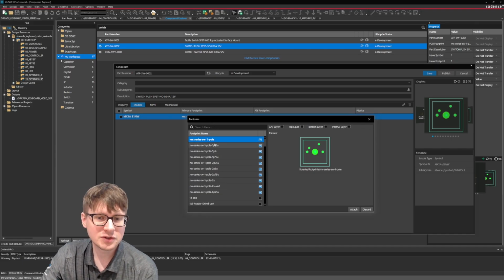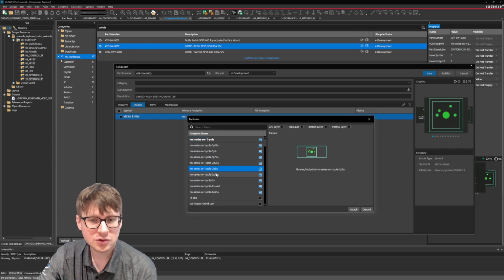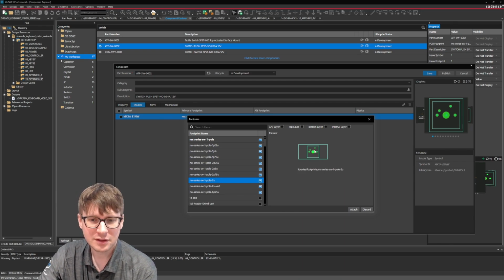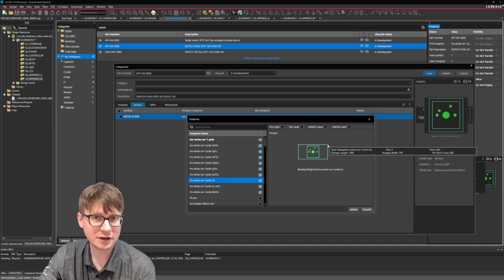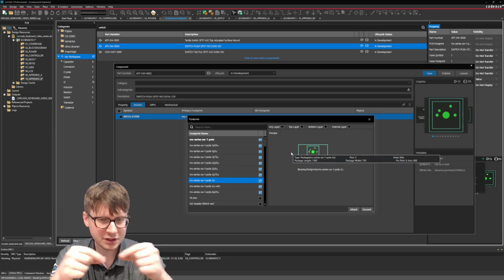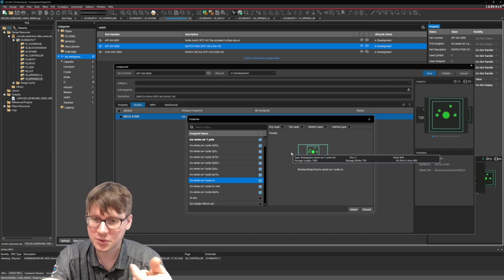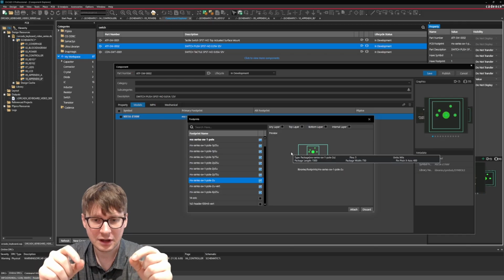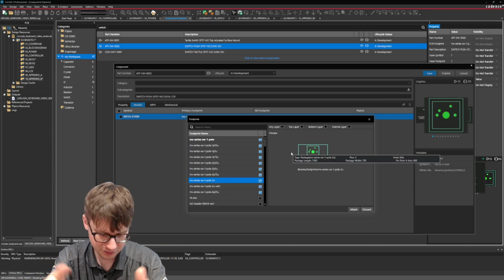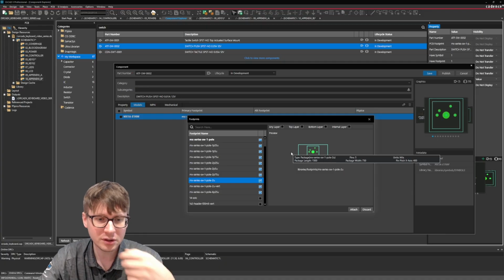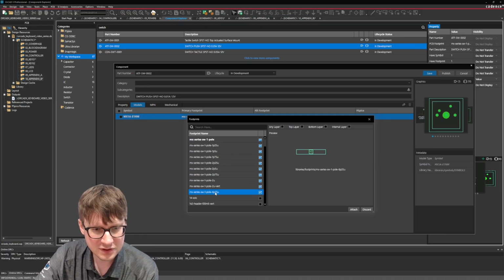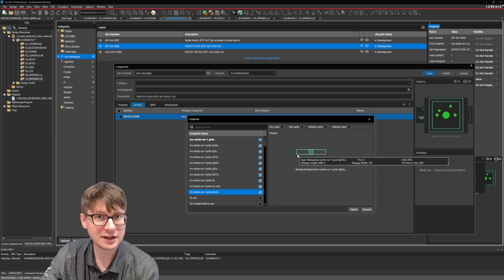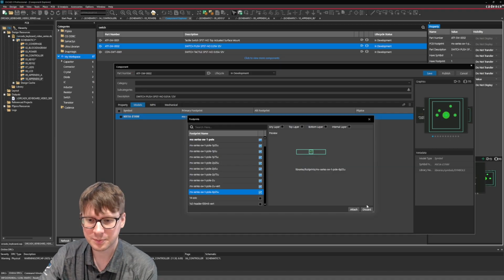But then we can simply use our right-click command or in the properties and choose one of these alternate footprints, which in this case, they don't have any different number of pins. They're simply just a wider version of each of these switches, right? So the switch component itself is just going to have the left side of the switch, the right side of the switch, and then maybe some mechanical holes for stability. But the keycap itself might be a little wider, right? So for example, our spacebar is the widest key on the keyboard. So if I look at this 6.25U, I'll talk about that in a second. It has this wide area here already designated for the entire spacebar keycap.